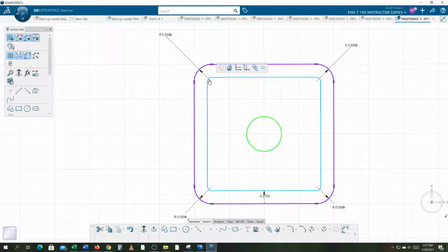there's no problem. See, there's still corners around here. I know that it's able to do that. The toolpath, if this were the case, doesn't have any discontinuity and tangencies. That means that this line blends tangent to this curve, and this line blends tangent to this curve, and so on around. A perfect square has 90-degree turns in it, so it doesn't like that.